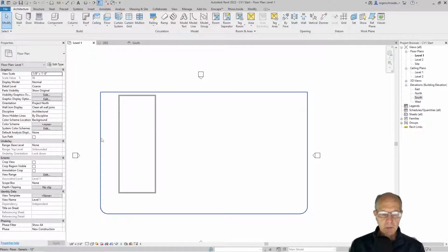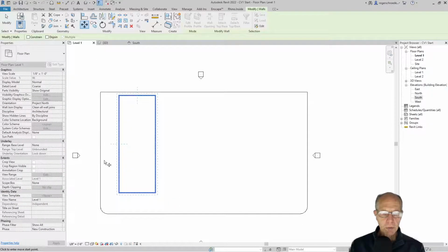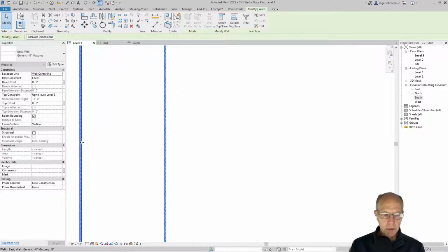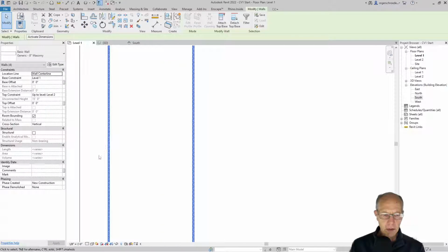And I want it to be 10 feet off of both the front and the side, as if it was a setback. So I'm going to draw a box around the whole thing. I'm going to grab my move tool. I'm going to come in here until I'm touching that outside edge and pull it over until I touch this one. And then I can move it back again. So now I know it's right on that edge. I'll move it back until it is 10 feet.